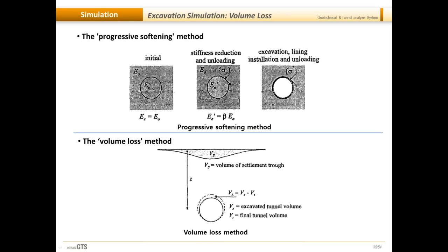But if you are working with finite element analysis, it is also worthwhile to perform a back analysis from this excavation to find out how much actual volume loss would have occurred. And depending upon the stiffness of the lining, even if let's say you have assumed 2% volume loss, you should activate the lining stiffness assuming the volume loss would be lesser than what is predicted.